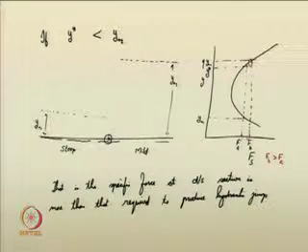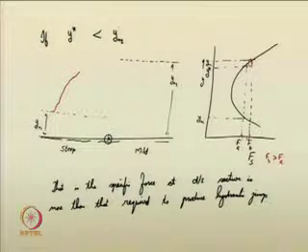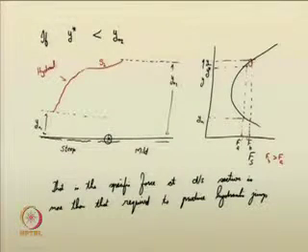The hydraulic jump is pushed here, it reaches y star depth, and from here it follows an S1 curve. So, this is your S1 curve, this is your hydraulic jump, and its sequent depth is y star. The pre-jump depth is yn1 and the sequent depth is y star. It is followed by an S1 curve, and it joins the mild slope channel with an S1 curve.